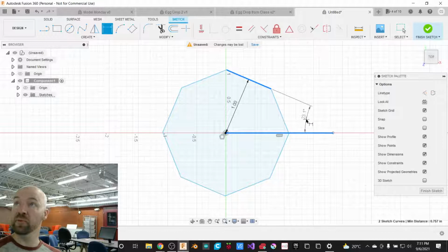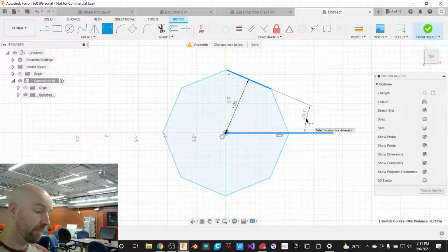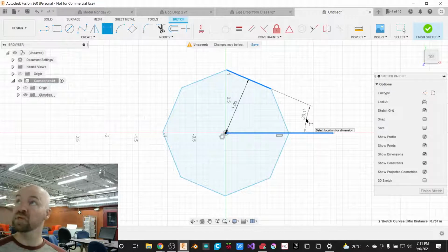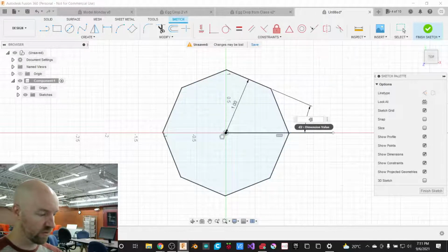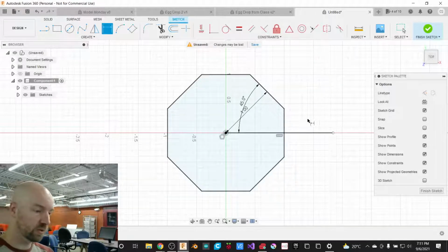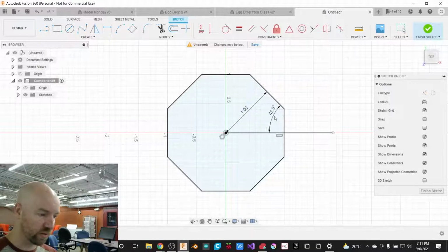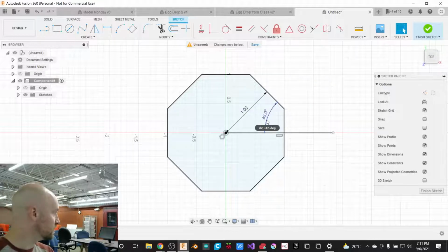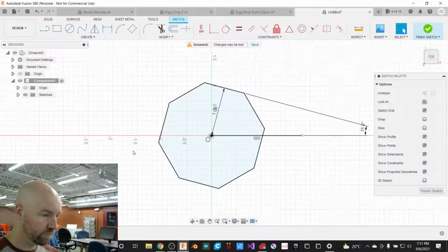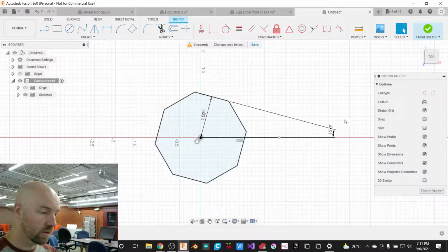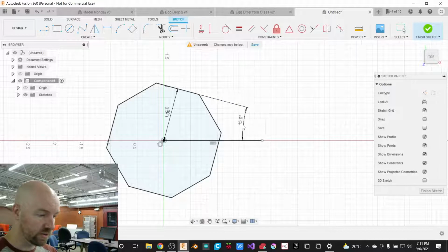And if I highlight both of those lines. Asking how to set the angle of your polygon? Yeah. Line. So you mean like? Let's say you want that in an exact 45 for some reason. So then I would just place that and then type 45, and then it'll snap that to a 45-degree angle. Does that make sense? Now I could change that to, say, 15. Okay. Yeah. And then these measurements you can put wherever you need them to be.